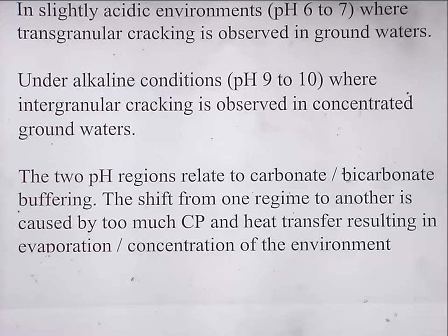Just going back to the crack shapes for a minute. The cracks are very interesting because the crack front, you know, where the edge of the crack is, is different under different conditions. It knows about the stress field. It senses the stress field, and it knows when it's getting near to the edge of a body, a component. And cracks actually change direction and things. They respond to the stress field, and they respond to the shape of the component.